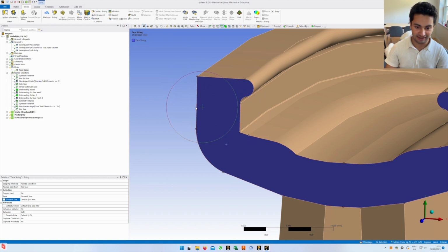So say in this dimension, which is the X dimension, we want this to be split into 2 across. Right now, 1 element is actually going to be too big to even fit there. So we could, let's try 3mm.